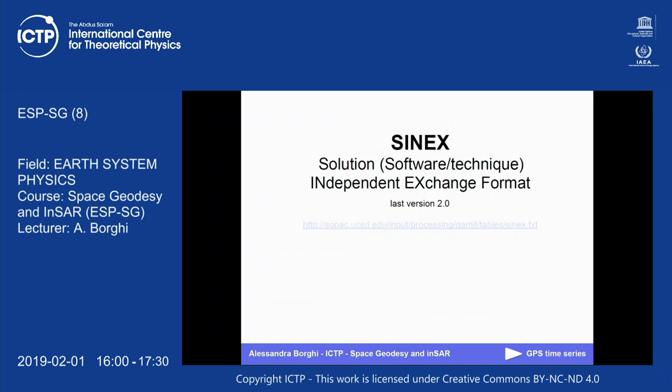We also have a format to share your solution, the result of your processing. I have computed my solution, that means the components of the baseline, the covariance matrix, the parameters that I have estimated or constrained, and they are written in this file called SINEX, Solution Independent Exchange Format.